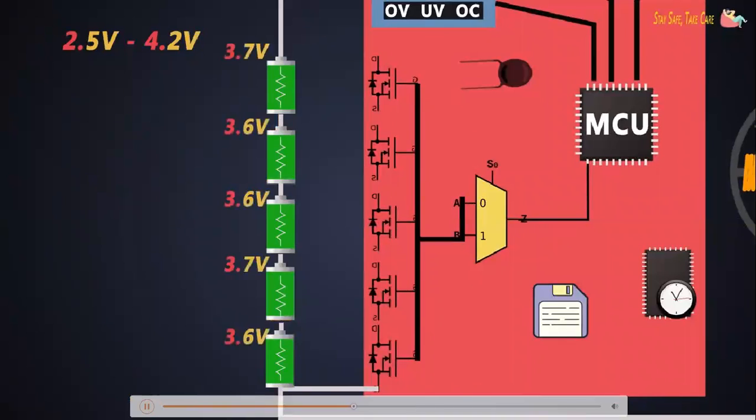The nominal voltage and temperature of the cells will slightly vary and differ from each other. So this weak cell heats up and its lifetime gets reduced. The weaker cell trips the discharge limit first, leaving the remaining cells with charge remaining inside. This can be overcome by cell balancing.